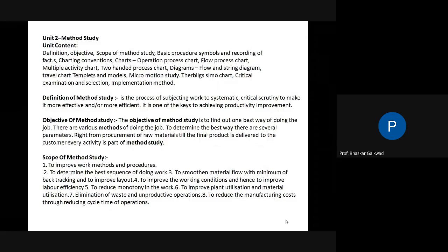A very simple thing is that while doing any job on a lathe machine, turning, facing, chamfering. Correct. So while making these jobs, while facing, you can go for chamfers. No need to keep a separate operation for chamfering. Like this way, unnecessary operations we can reduce. While facing, you can give the chamfers. Correct. It is not necessary to make a separate operation for chamfering.